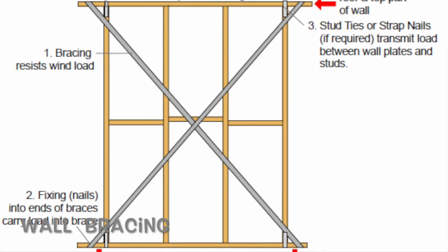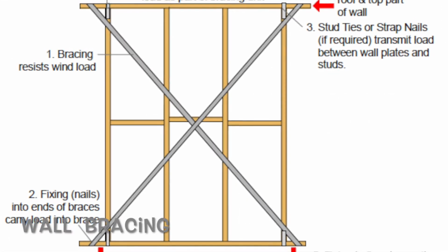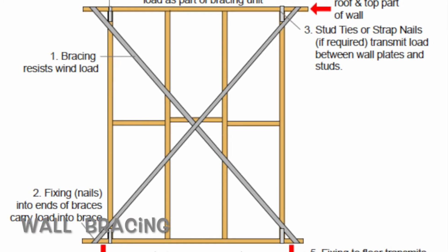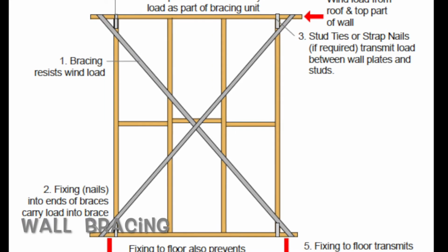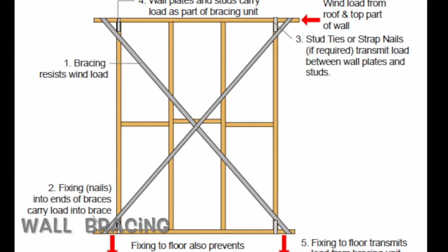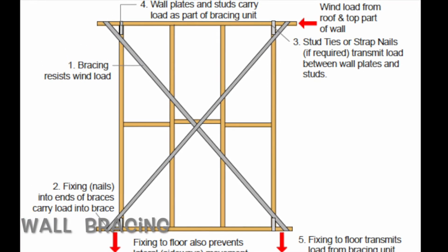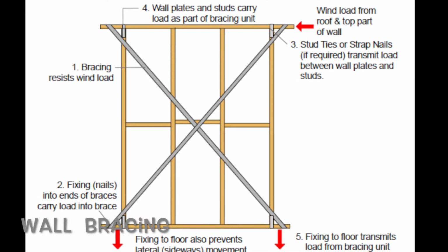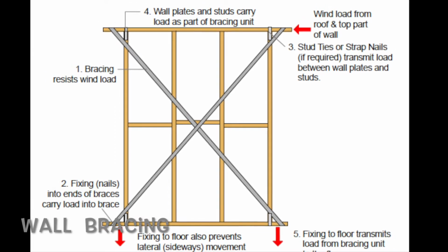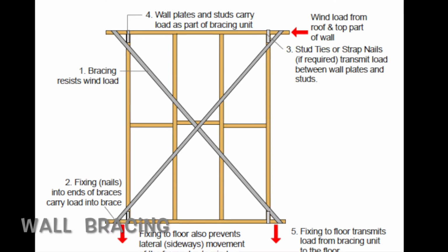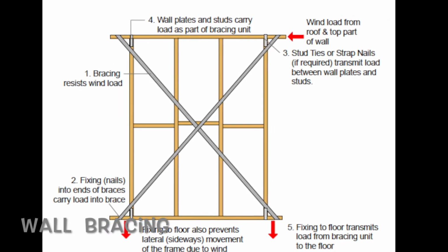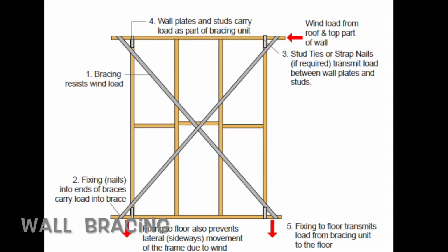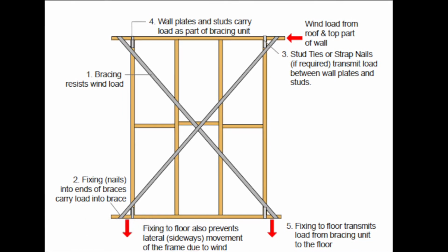Wall bracing is quite similar to roof bracing in the calculations. It was found that the force in the tensile diagonal member is 41.39 kilonewtons. A suitable equal angle section must now be selected from the capacity table. The smallest section for this wall bracing is 50 by 50 by 3 EA. As well as being able to sufficiently carry the load, it will also be the cheapest possible section.